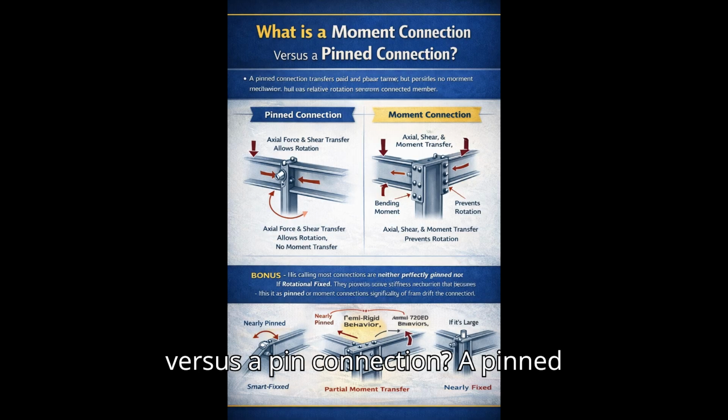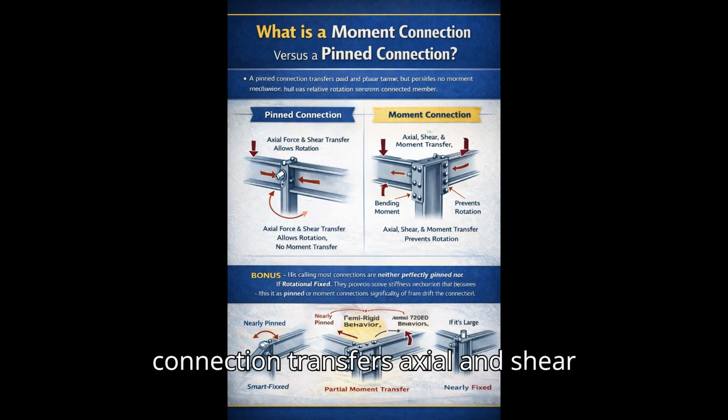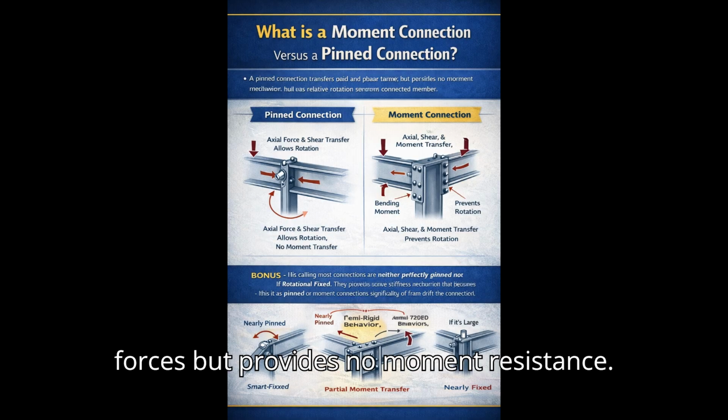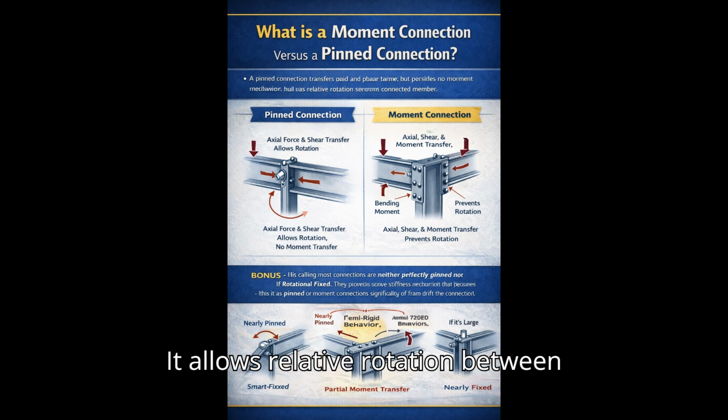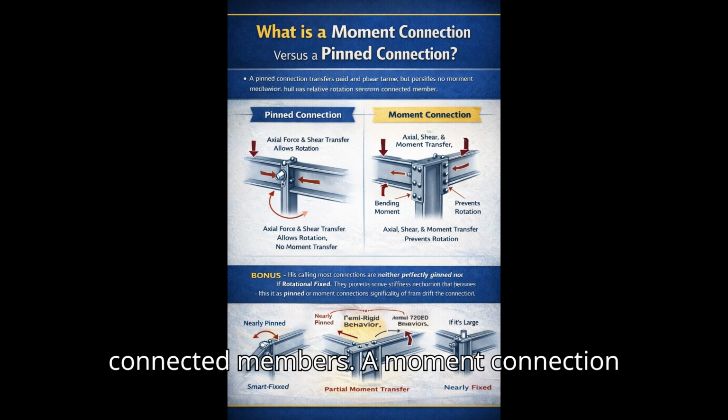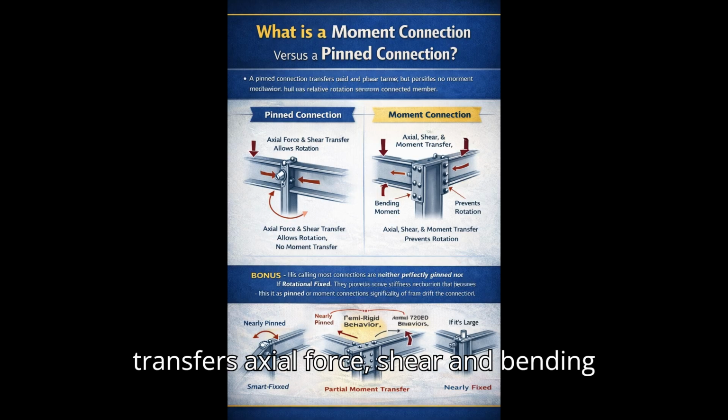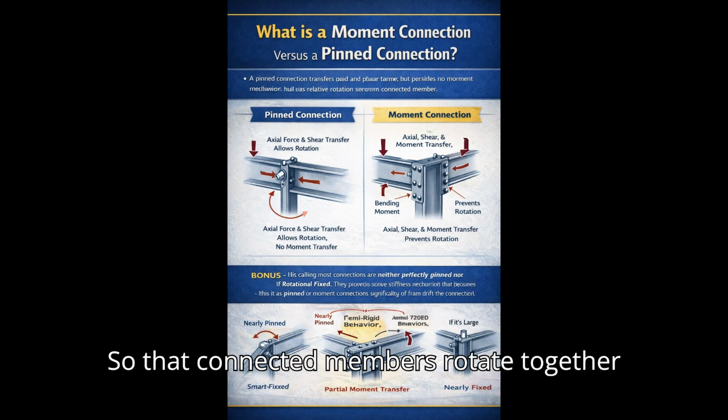9. What is a moment connection versus a pinned connection? A pinned connection transfers axial and shear forces but provides no moment resistance. It allows relative rotation between connected members. A moment connection transfers axial force, shear, and bending moment, and restrains relative rotation so that connected members rotate together after deformation.